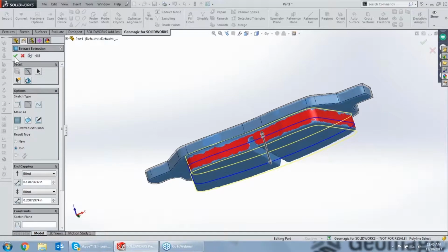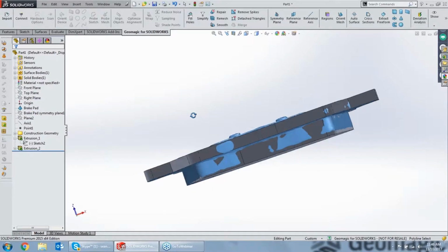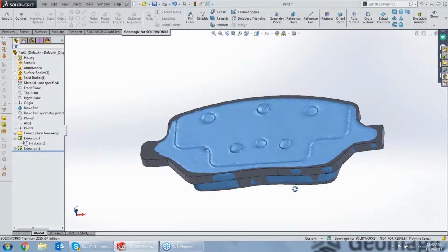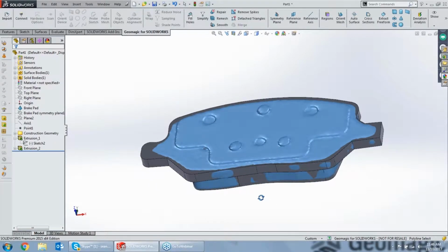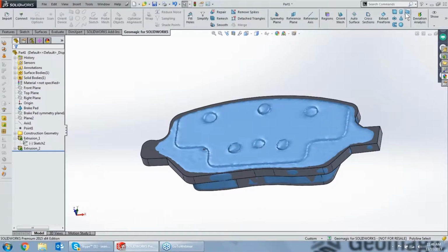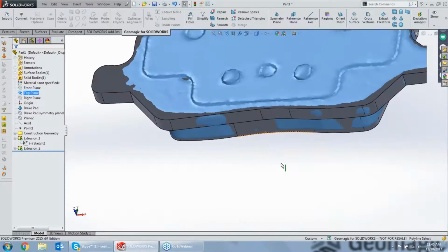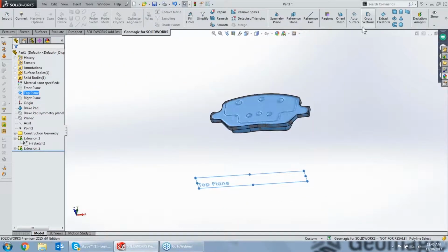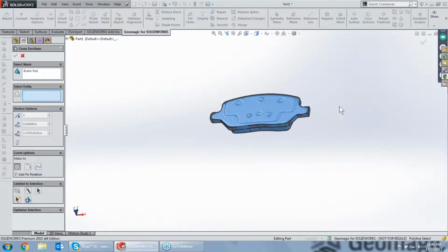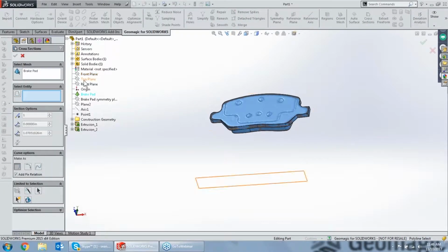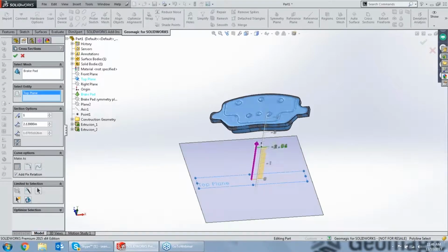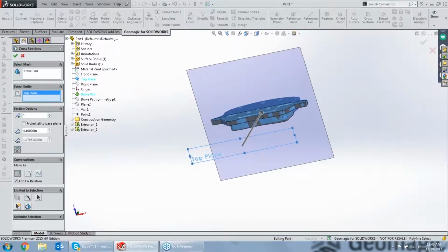So I'll go ahead and join this new body that I'm building with my existing body. And if I get to a feature where I maybe cannot use one of these extrusion or revolution or even a primitive geometry tool like my cylinder tool, I always have manual override. And what that's going to look like is, let's see, probably this plane. Yeah, we'll use that plane. And I'm going to focus on this tiny little feature down here. I can always manually override and extract a cross section from an existing piece of reference geometry. And of course, this is really far away, so I'll drag that into my part.